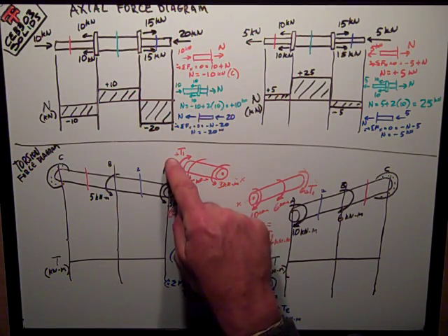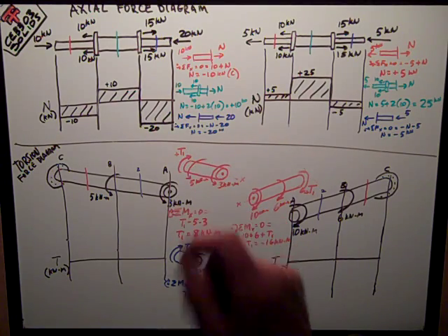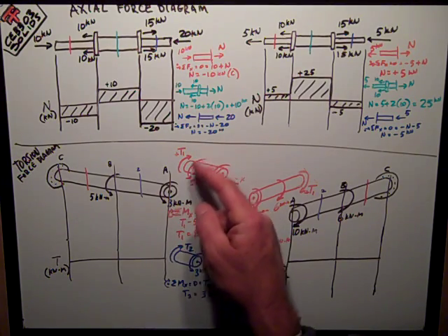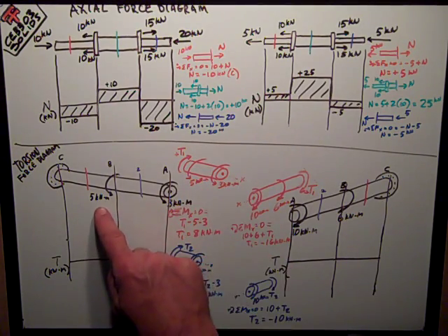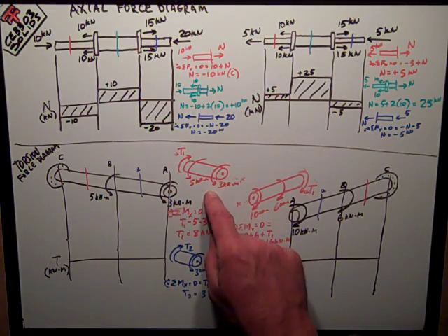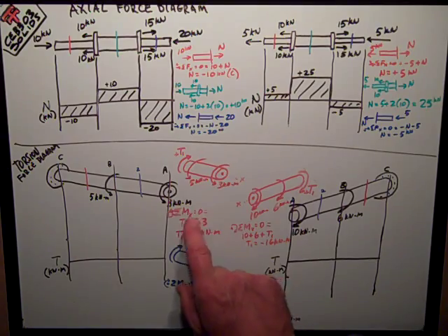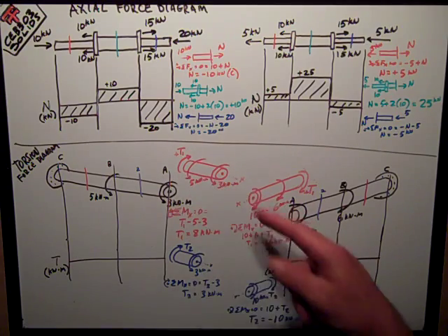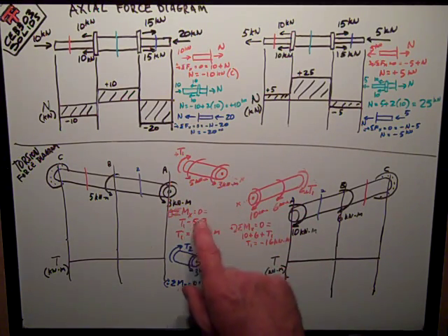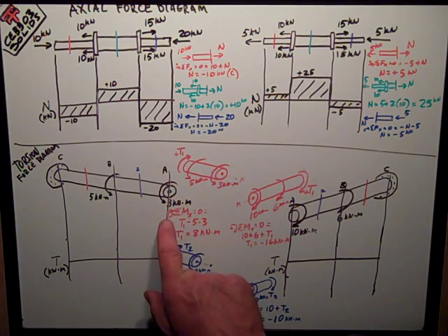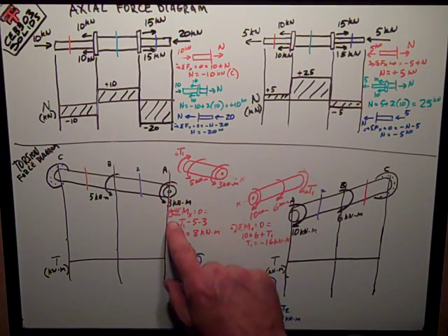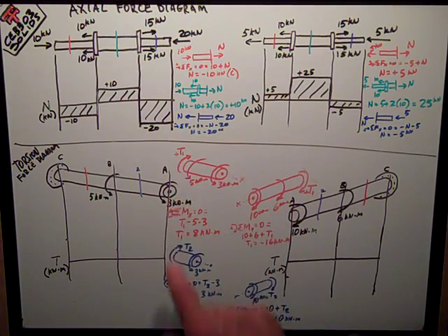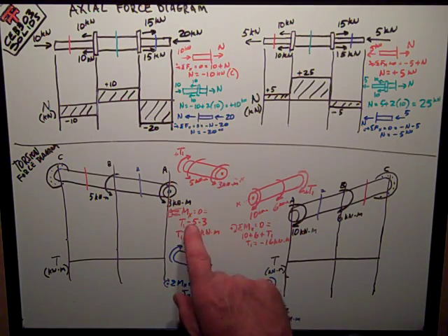And that's how I've drawn my internal force T1 curling over the top, which is the opposite direction of my 5 kilonewton meters and 3 kilonewton meters that are applied here. I just do a sum of moments about the x-axis, which is this axis passing through the longitudinal direction on the shaft. It's equal to 0. I assume positive is over the top, but this just happens to be the positive direction for internal torque, internal torsion.